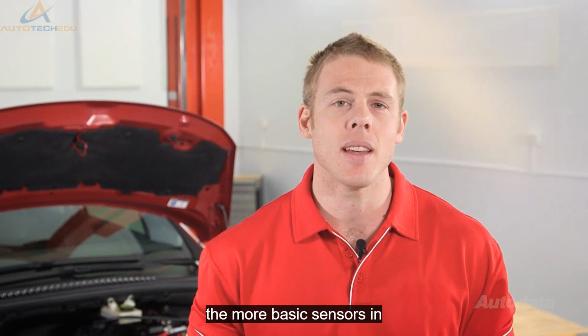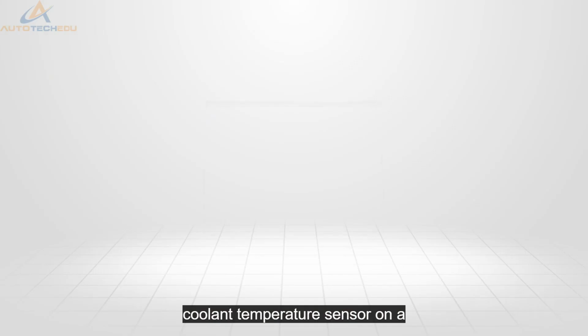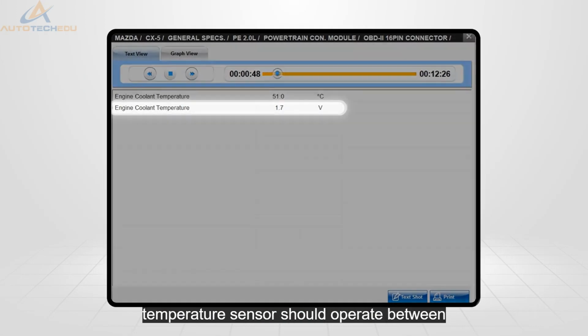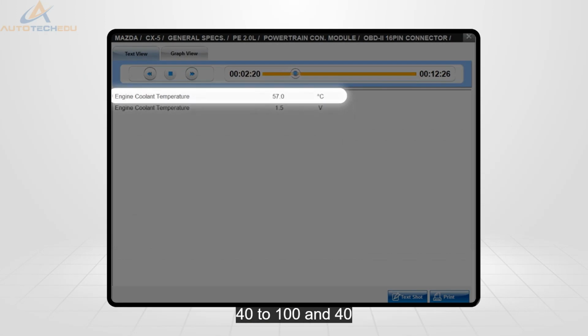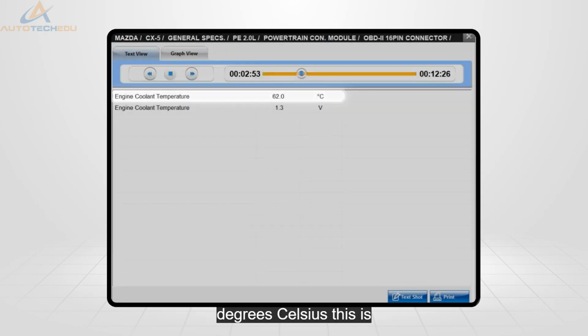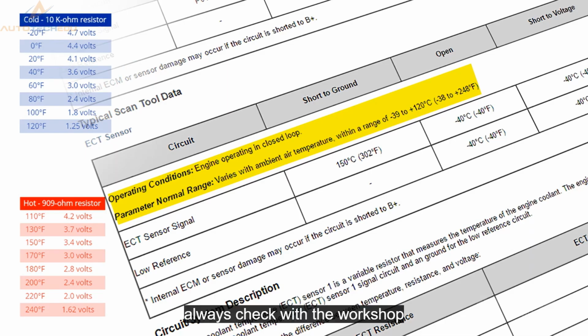One of the more basic sensors in the automotive vehicle is the coolant temperature sensor. On a correctly operating vehicle, the temperature sensor should operate between 0.2 to 4.8 volts and a temperature range from -40 to 140 degrees Celsius. This is what a correctly operating sensor should look like, from cold start to warm idle. Always check with the workshop manual for the correct operating temperatures.